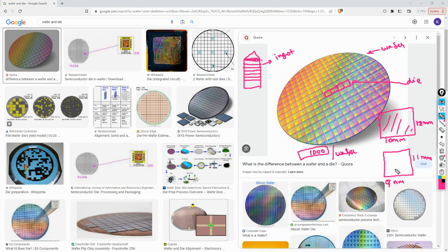You have done some extraordinary area planning, what is needed and what is not needed. If you are able to bring down this size, then on the same wafer, I'm just giving you rough numbers, you will have say 1,200 chips per wafer. The die cost comes down when your area is lesser. So people always prefer packing more and more chips in a wafer, to reduce their manufacturing cost.